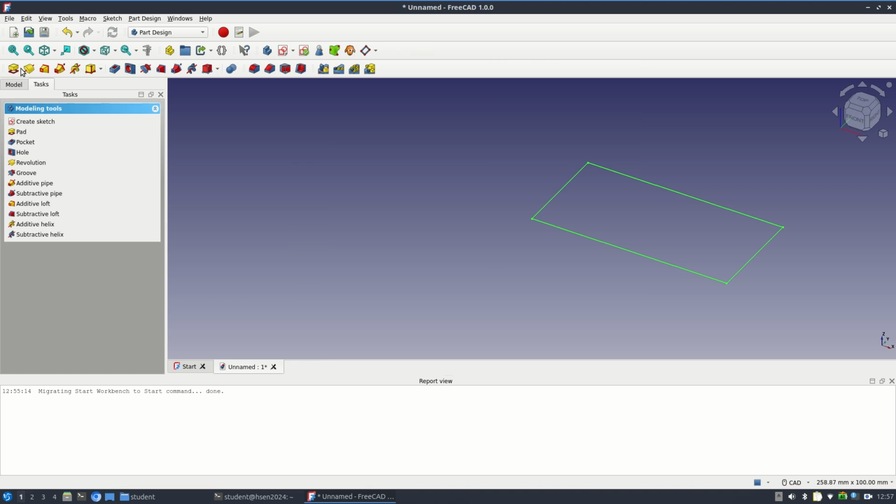So now, what's the thickness of my material? So I went there and I measured the stock that we're gonna use to cut, and the stock is about 13 millimeters thick. So what we're gonna do is we're gonna shoot for more, so we make sure that we cut through, but then as it cuts on the CNC, as soon as it cuts all the way off, and it pops off, then we can just hit the stop button, right?